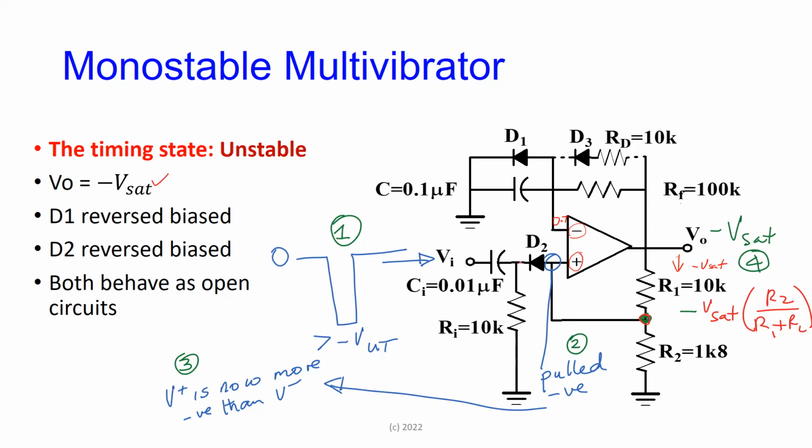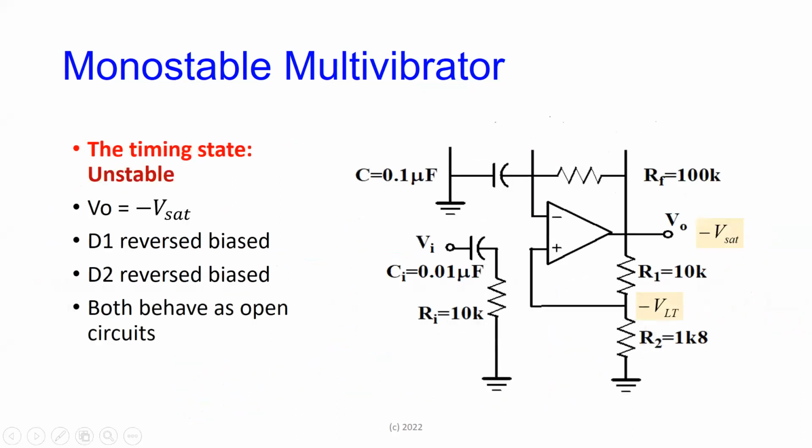So at that point, once I put the negative input here, Vout goes to minus VSAT, and then notice what happens. If here goes to minus VSAT, here is now negative, so this diode is now reverse biased. Because of the same virtual earth behavior that I spoke about, here is going to go negative, so this diode is now reverse biased. So both of them are now out of the circuit. And like we did for the precision rectifier circuit last week, let's erase them. So this is what the circuit now looks like.